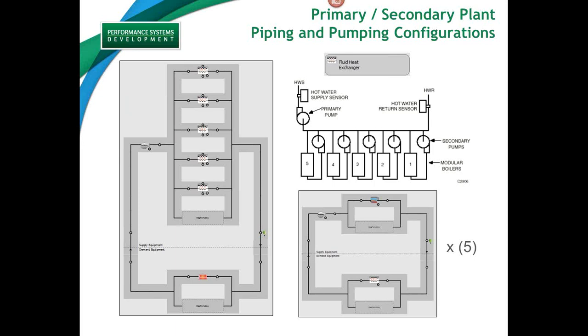And then to complete the design in OpenStudio, the user would create a 6th loop, a 6th water loop. And in that water loop, they would assign the 5 fluid heat exchangers. It's the opposite side of the heat exchangers. So this represents the distribution loop, or the primary loop. So yet again, it needs another pump. It has the supply coming from the fluid heat exchanger. It has another set point controller telling that distribution loop, what are you trying to do? Are you trying to send constant temperature water through that loop, or some sort of reset through that loop? And then, of course, the loads.